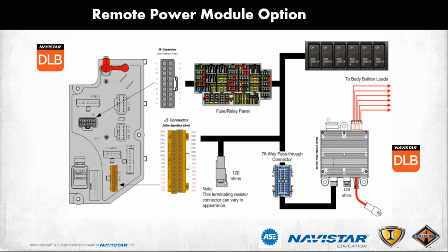With a simple input signal in here, we can program it to look for ground or look for 12 volts. And there's one in between called floating. So when he pulls that lever in the back, it can signal this RPM module to ramp the engine just for the compactor or whatever device. So we can use a black connector for throttle control at times.